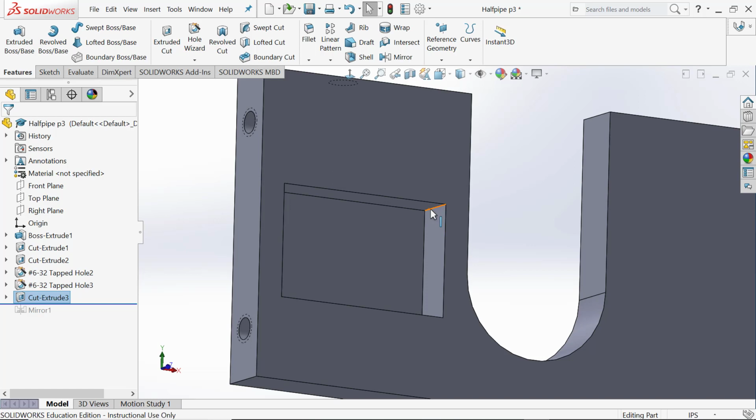All right. Click on that sketch briefly. You put your sketch on the mid plane. That's why. So there actually is a hole in there. It's a cavity inside of your part. Okay. No, let me show you how to fix this because this is kind of cool. Let me go up front. I'm going to show you all of you how to fix this.